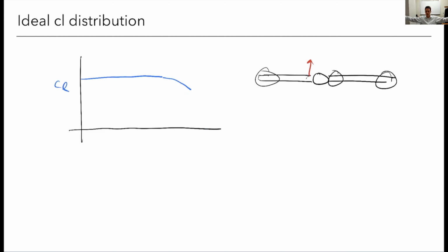By deflecting ailerons way out here at the tip, I get a bigger leverage, so I don't have to deflect my ailerons as much to get the turn that I want. If they were too close inboard, I'd have to have big deflections to get the rolling moment I want, so I want to put them out. And if I'm stalling out where my ailerons are, then I don't have the control that I need.